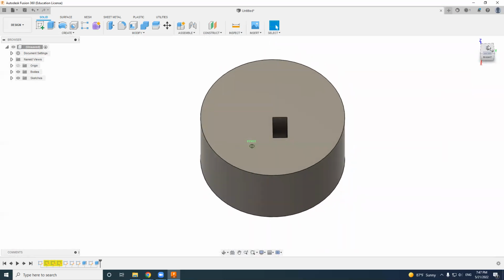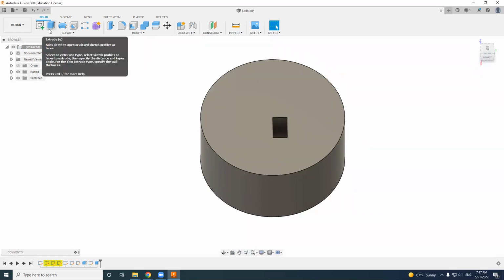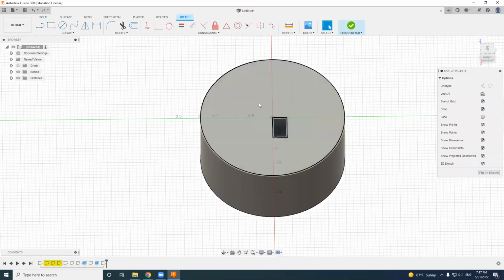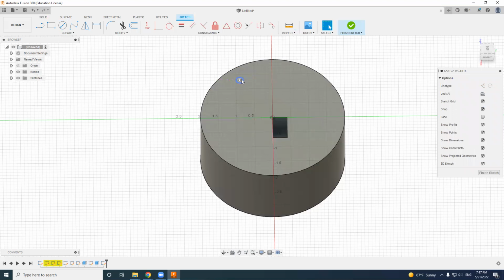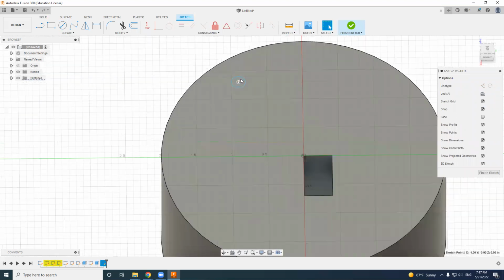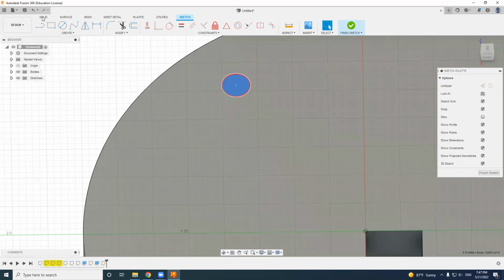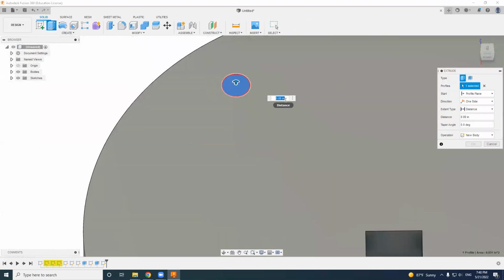Create this part, this cut. And what about if I want to add some screws and or threads, right? And here, first of all, we need to create a hole. Find this surface, and then do a sketch. Maybe I'll create a very tiny hole here, and give it a little bit of depth, make it bigger, say negative 0.5.